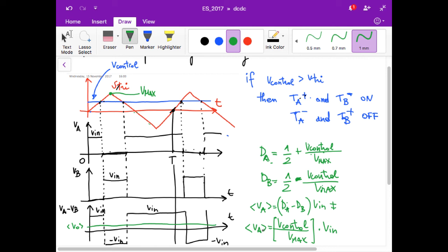It's something that is done inside the microcontroller with a code. Basically, the triangular wave function is just a counter that goes up to a maximum value, then decreases and then goes up, so it behaves like a triangular wave, and V control is a reference number with which the variable which represents the triangular wave function is compared.